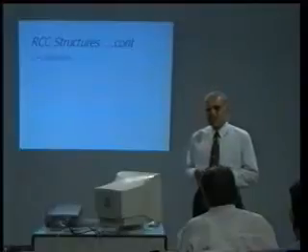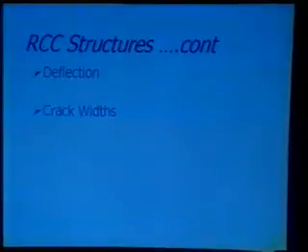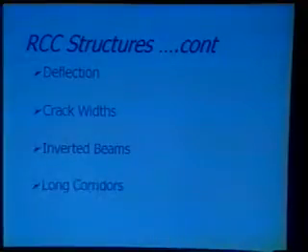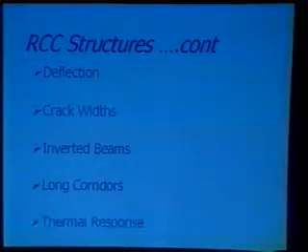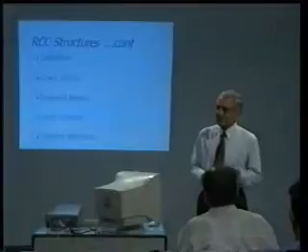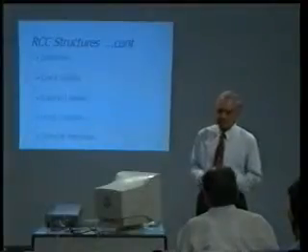Then you have the criteria of deflection, the crack width consideration, the problem of the inverted beams, the aspect of the long corridors, and the thermal response, particularly in this part of the country where the winter temperatures and the summer temperatures are so widely variant.